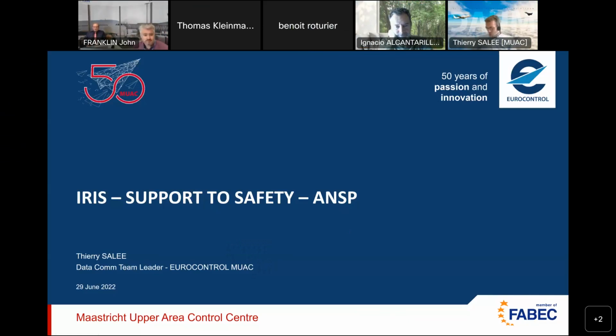Thank you for the introduction. Maybe because the public is wide here today: MUAC is the ANSP in charge of the upper airspace above Benelux and northwest Germany. And indeed, we have been active in data link for many years already. Data link is initially CPDLC, which is used for pilot to controller communication, exchanging text messages. And nowadays, with the second version of ATN baseline 2, we started the deployment of ADS-C, which is not the follow-up of ADS-B, but it's really a data link application.